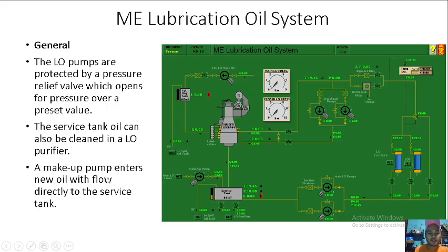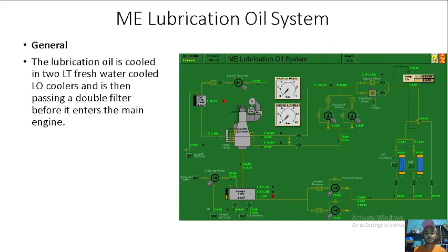A makeup pump enters new oil with flow directly to the service tank. So if the service tank level goes down, we can turn on this makeup pump to give more oil to the service tank.